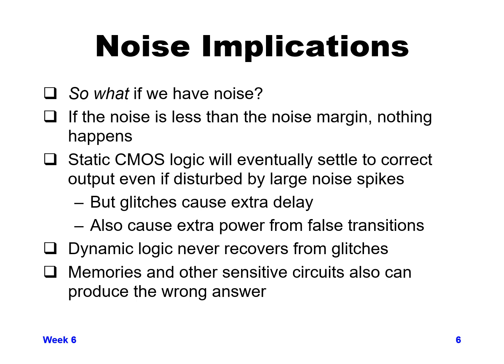And one thing that I'll make a note of that's not on this slide is the really difficult thing about noise is if you do have a noise glitch that causes a real problem, it tends to be very hard to debug, because it's very dependent on specific signals, the order in which wires are switching over time, and it's not necessarily repeatable in a way that other failures are repeatable.